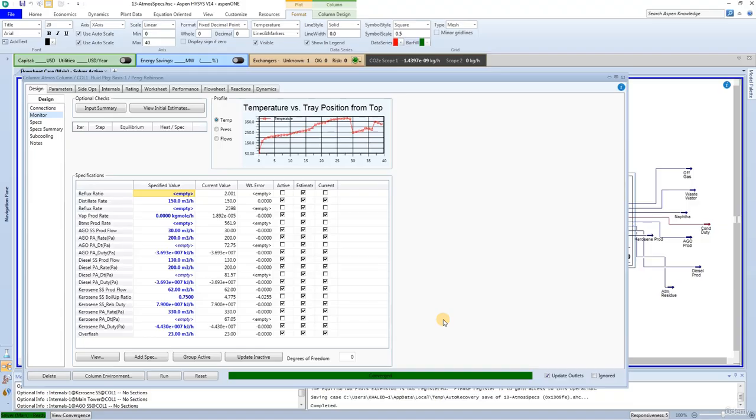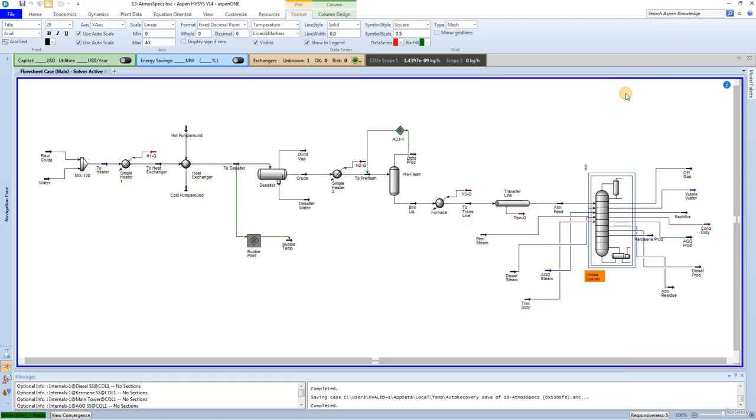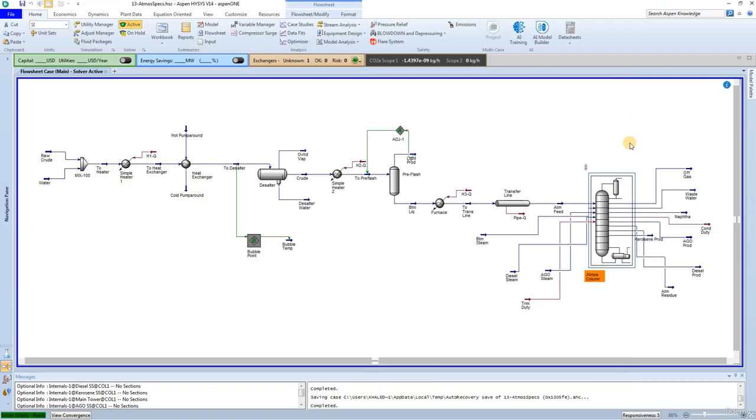Before you maximize the production of the various products, the base case needs to be defined. Attach petroleum assay analysis to the 4 primary atmospheric column products: naphtha, kerosene, diesel, atmospheric gas oil.